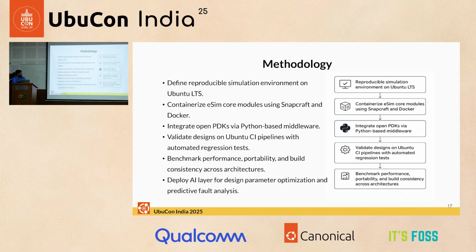The methodology that we follow is a reproducible simulation environment on Ubuntu for long-term support, containerizing the eSIM core modules using Snapcraft and Docker. That's the methodology we follow to get eSIM on Ubuntu supported for Snapcraft and Docker. We also integrate open PDKs via Python-based middleware, as we already talked about, the Google SkyWater and the IHP, and we benchmark performance and portability with these.